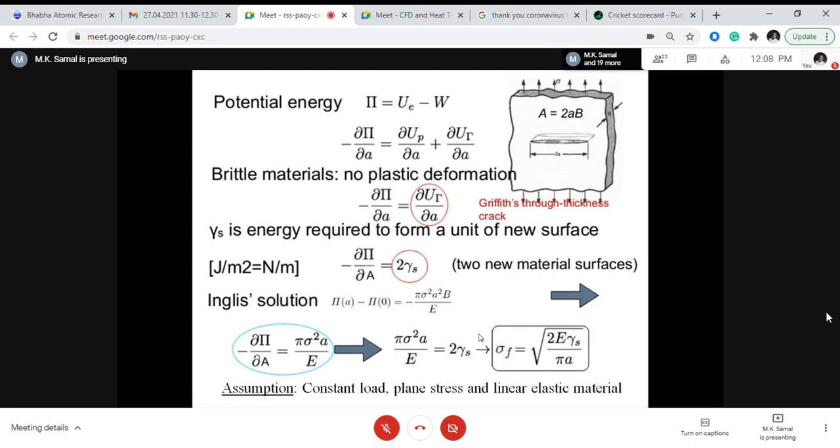So with the same material, you do the test. Of course, it has to be irradiated material. You calculate the critical stress intensity factor K1C, so that becomes your material property. Then in your actual vessel, you model how much stress comes from the loading condition, like internal pressure, axial load or thermal stresses, and you know the crack length. Then you multiply the remote stress by the crack length, and also by the geometry factor, which is quite different from 1, and that is called K1. That is the applied stress intensity factor. That is our loading parameter.